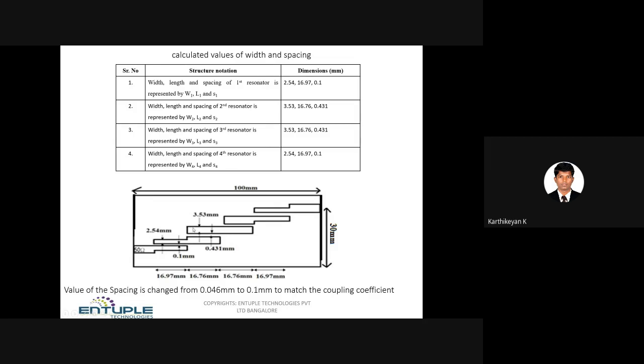Anyway, we are going to create the first one here, and then we'll create the second one, and we will duplicate this again, and this is the last one. Once you have created this one, we will create actually two, and then we will connect and duplicate again here. So this kind of parallel coupled filter we can easily create using the duplication method in HFSS.